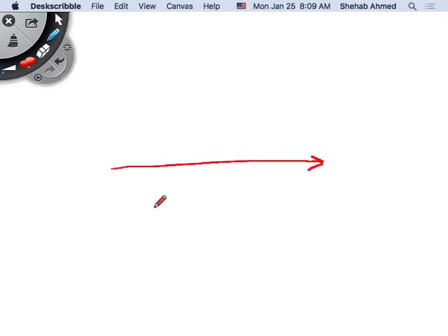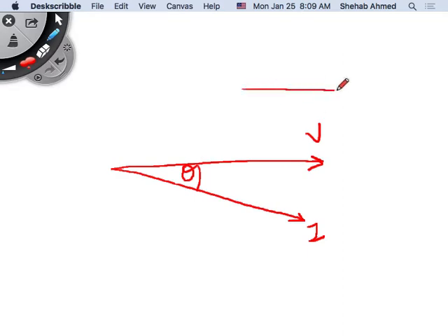So we talked about lagging and leading power factor last time, right? So we said that if V is here, I is here, right? So this is lagging power factor. But because of the use of the conjugate, when we draw the power triangle, we drew it this way, where S was here, and this was the same power factor, and this was the reactive power in the system. So I don't know why we use the conjugate, but what it does is sort of confuse you a little bit when you draw the power triangle.